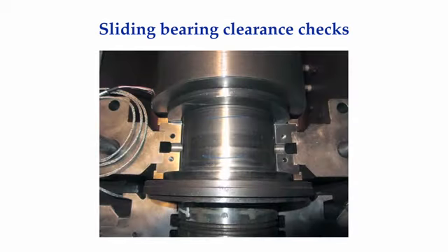One method is to use a product called Plastigauge. Plastigauge are pliable strands that can be purchased to measure gaps from 1 to 70 mils and comes in 6 different sizes for different gap measurement ranges.